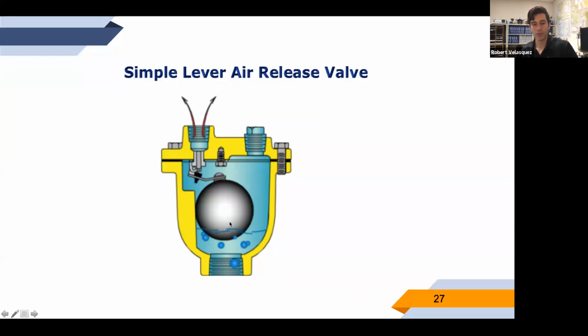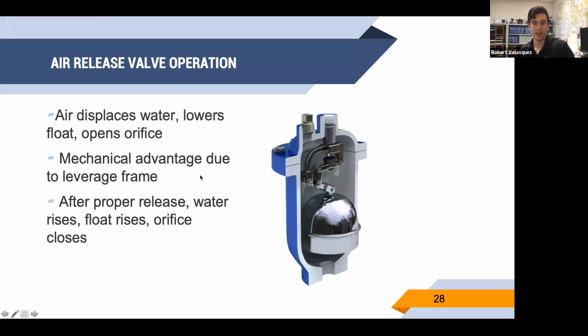And when your water comes up in here, it's going to push that ball up, and it's going to close the orifice. When air collects in here, it'll displace the water, and the water level will drop, so the ball will drop, and it will let air out. And when that lets air out, the water fills back up, and it brings the ball back up, and it closes that. And so we displace that air as the ball drops.